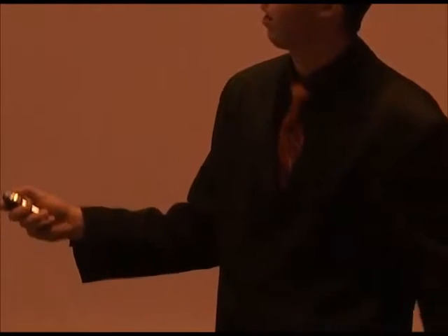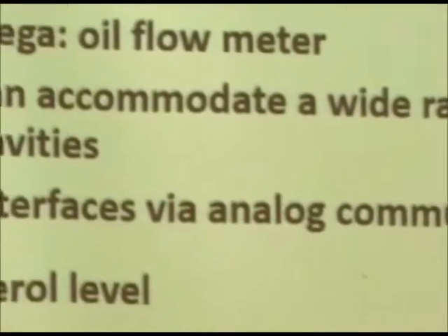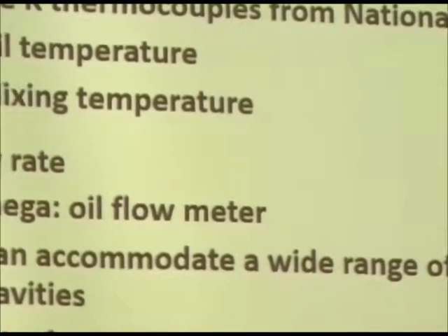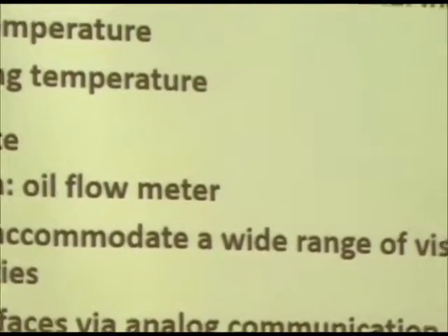One of the problems we have with automating the system in the future would be maintaining the glycerol level. The state inside of the reactor is continually changing, and the glycerol itself is a very thick fluid, so it doesn't flow continually. It builds up and then flows through really fast, breaks away. So it's hard to measure that depth. Dr. Parnas, the original maker of this design, himself said that depth measurements were very hard to make. They ended up using a radar system that could do it. But we didn't tackle that challenge at this time.